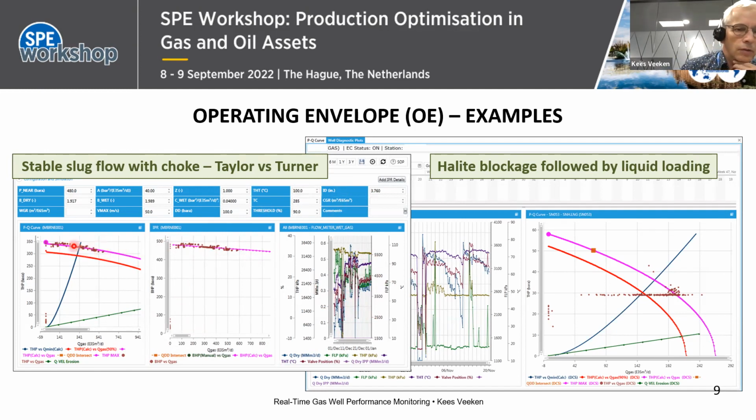In this case, you see how points are hovering quite high. We're operating this well at a very small choke. It's still a new well, so you see flowing tubing head pressures are above 300 bar. Another aspect is that at those pressures, with that large pressure drop across the choke, liquid loading doesn't really happen where you expect it to. Like the Turner velocity, you can actually operate quite easily far left of the liquid loading rate without seeing any instability. You see that clearly illustrated here.